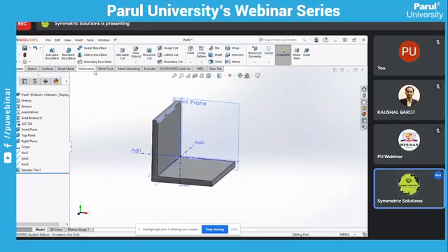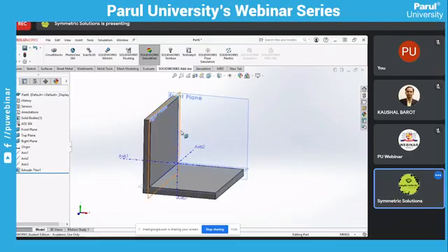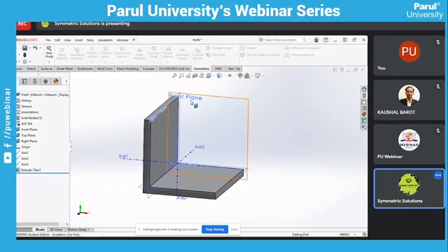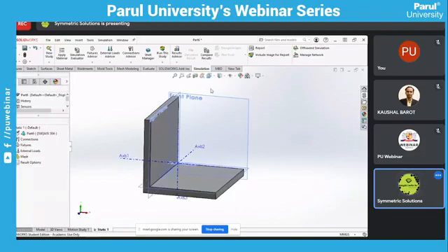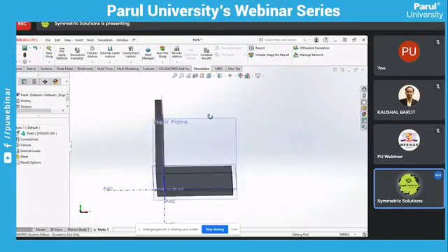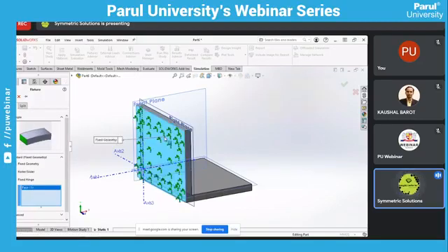Now, in SolidWorks Simulation, define a new study of static structural analysis. Give OK. Now define your fixtures. First, as a finite element analysis, define your material. After material selection, define your fixtures. Like if your product is fixed with some different environment, or rolling or sliding, or fixed hinge or elastic supports, we have fixed geometry, this face.